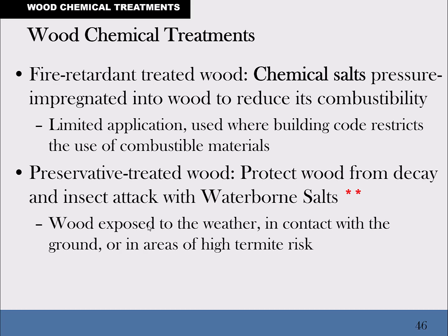So again, there are some places where you can get away with a little bit of wood in a commercial code if it's treated for fire retardancy to keep it from burning. And so typically it'll be some kind of a salt. Whereas preservative treated wood, that's the stuff to preserve against bugs, from insect attacks. And so that's a different kind of pressure treated treatment, which is the one we're most familiar with day in, day out. It comes from,